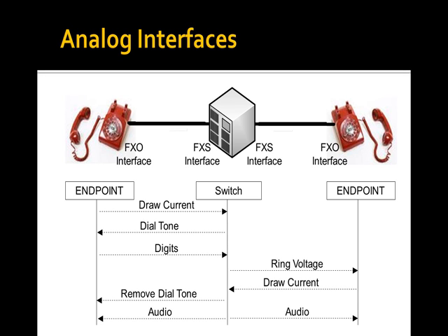I'm sorry? FXS sends current, does it also send the ringing voltage? FXS draws current, doesn't send current. I'm sorry, I said that backwards. Like I said, it's confusing. FXS provides current. You're absolutely right. Does it also provide the ringing voltage? Yes, it provides current. It provides ringing voltage. FXO draws current, sinks current's the term, and receives ringing voltage.